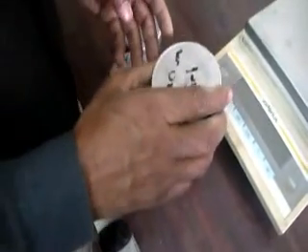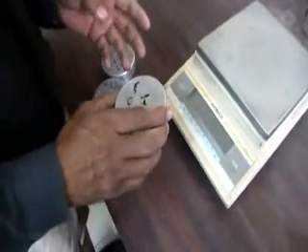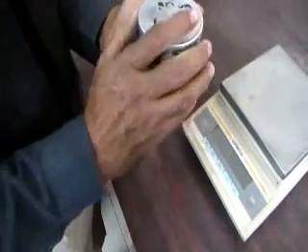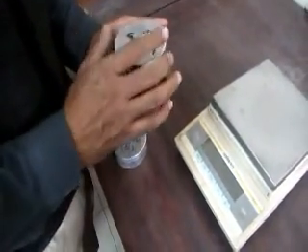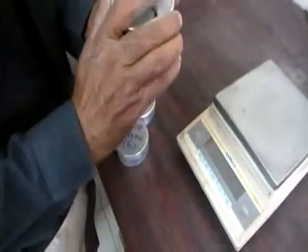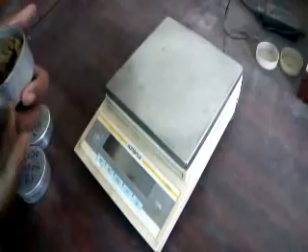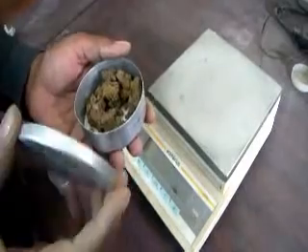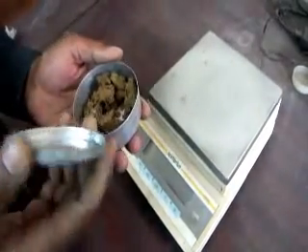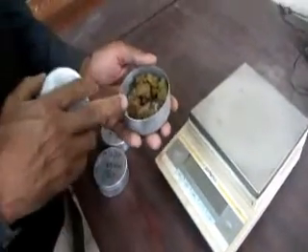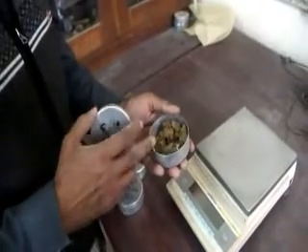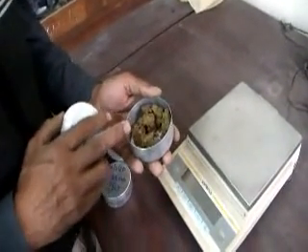Before putting the samples in the oven, which is working at 105 degrees Celsius for 24 hours to remove the soil moisture, we need to find out the weight of soil plus sample box for all. After 24 hours we will measure the weight of sample plus dried soil. Then we will remove the soil and find the weight of the empty box, to find out exactly the soil moisture that was absorbed in this amount of soil, to finally find the volumetric content of water in this soil.